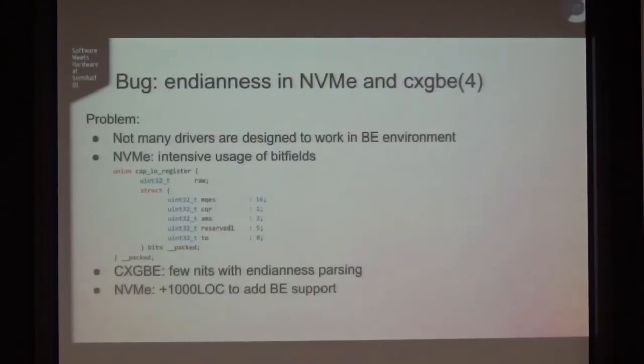Yeah, the next bug is a reprimand for all developers, including myself. As I said, the PowerPC 64 is a big endian system. So once we got to the point where the PCIe was up and running, we tried to attach any drivers which were on the system. Unfortunately, there was only one driver which worked. It was the XHCI USB interface.